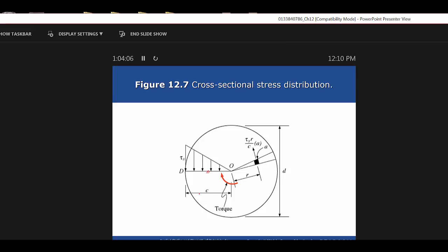Then the allowable torque, again, we're using the same type of thing: 83 newtons per millimeter squared times the 25.7 times 10 to the 6 millimeters to the fourth, which was the polar moment, and divide that by the 75 millimeters again. And that's the max out at the end, isn't it? That's why you have to use the 75 there.